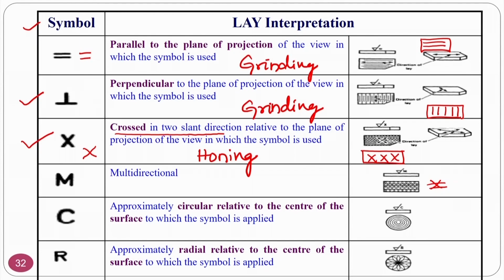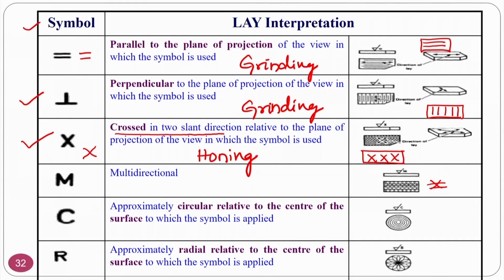Whenever you club 2-3 processes, in some cases it is a harsh process, like surface roughness is very high. Whenever you go for a secondary operation, then the finishing is going to take place. So, you will get a pattern which is there in a coarse grinding process, then if it is followed by a fine honing process, you will get a multi-directional surface pattern.